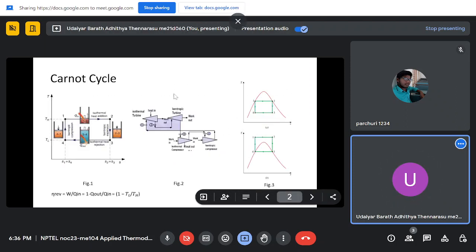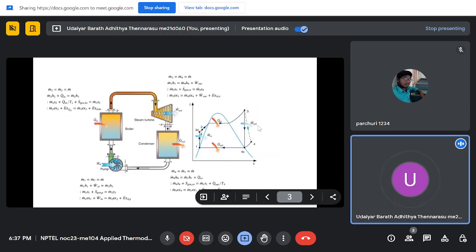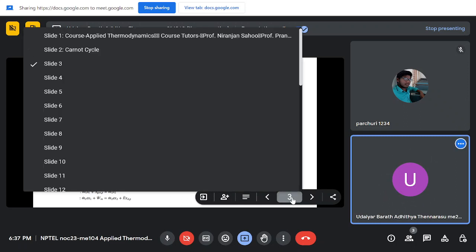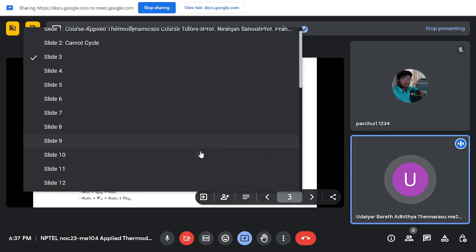You can see in the enthalpy and pressure-temperature diagrams that there will be a larger enthalpy difference in the compressor compared to the pump. So in the Carnot cycle it will take much more energy to compress, so the back work ratio will be larger in the Carnot cycle.